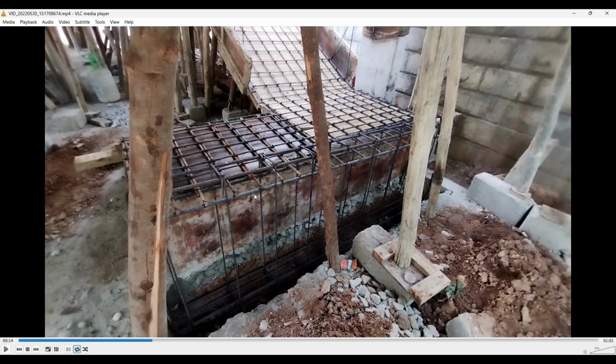If this was a load bearing beam, the beam which is actually subjected to wall loads and everything, then definitely we have to give the side face reinforcement because the depth is more than 750 mm. But as this is not a load bearing beam but just a top hidden beam that is being supported by the bars on the bottom, we have not given any side face reinforcement. If you want to give, you can, just spend some extra money, that's it. It is not going to enhance the strength of your beam as such.